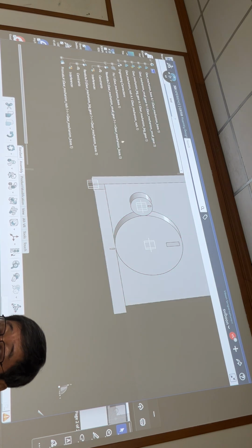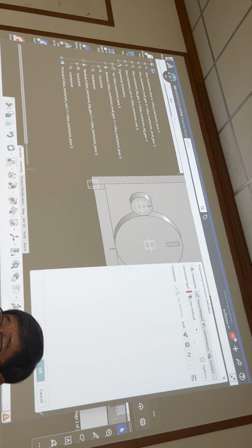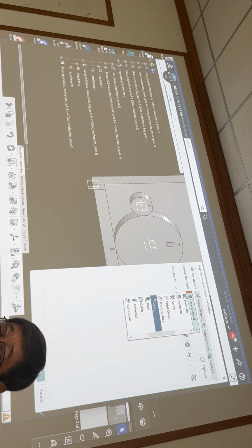Next, I want to create a joint between this one. If I use this one, it means that we need 3 inputs. We want to reduce to just 1 input. So we have to set one relation between this and this here, right? So that will be a gear joint. I use this one from the template. I'm using the gear joint, this one, right? Gear.